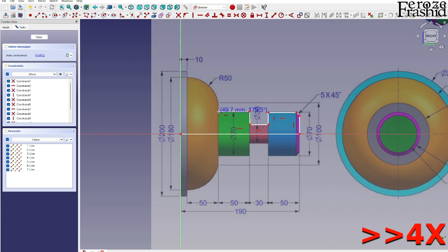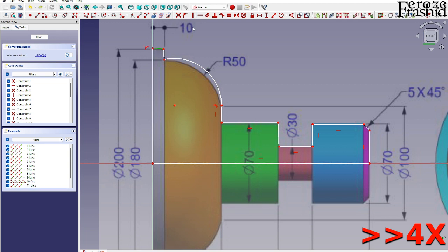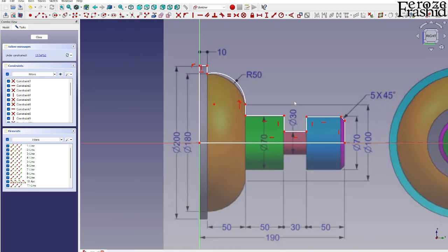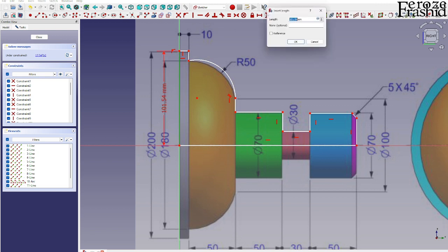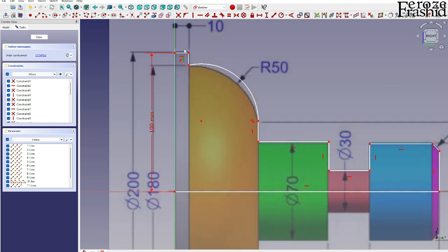So the image is on the YZ plane, that's what we want to sketch. And then quickly I'll draw the outline of this object. Alright, the outline is drawn. Let's go ahead and apply some constraints to it. This line is 100 millimeter. And this is obviously 10. It's given right there. This is a 10 thickness as well.